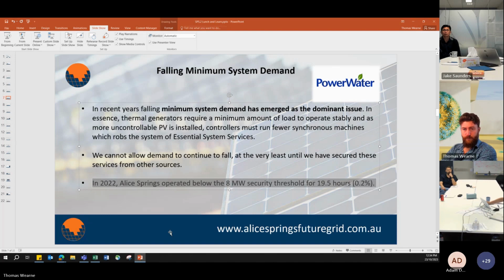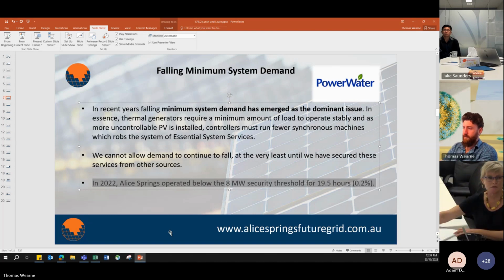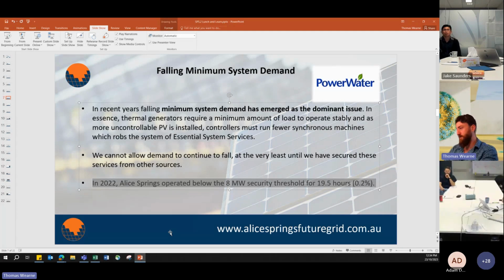And I assume that over time the number of hours a year that sites were constrained will be available and we'll build up that knowledge base. Yeah, and that's another really good point. It's the case today that if we could control new solar systems, we'd be turning them all the way to zero a lot of the time because there isn't enough controllable fleet to maintain the targets that we have. Once this would be most systems, they would all be sharing that burden, and that might mean you're only turning them down by 10 or 15%, and they barely even feel it. So a lot of it is about the equity of the controlled versus the uncontrolled population.